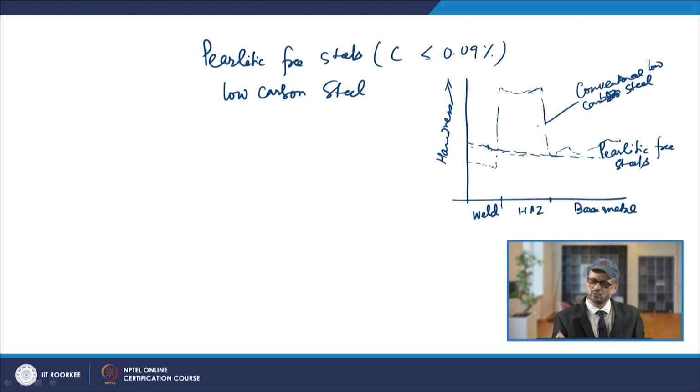Because of that you get this sharp rise in this range. Most of the alloy steels will show this martensitic or martensitic bainitic structure over the wide interval of cooling, from 800 to 500 degrees centigrade.